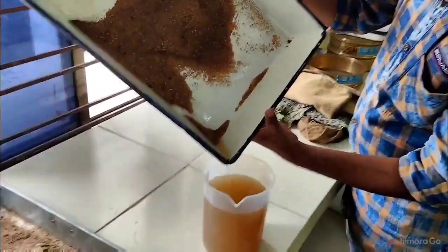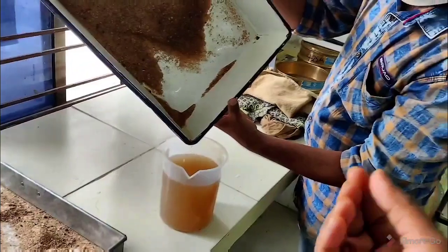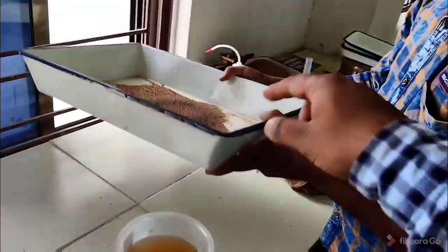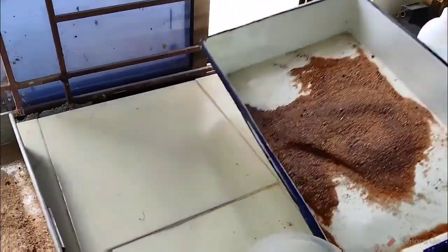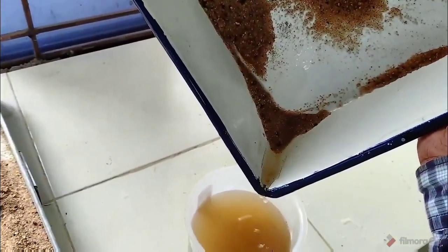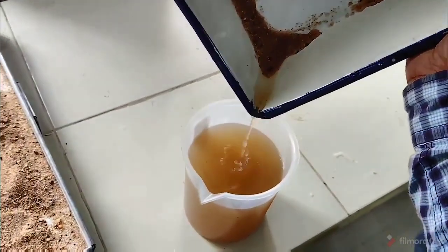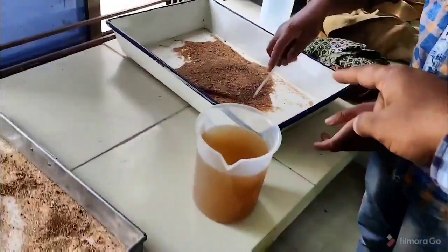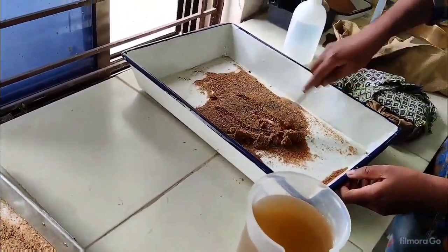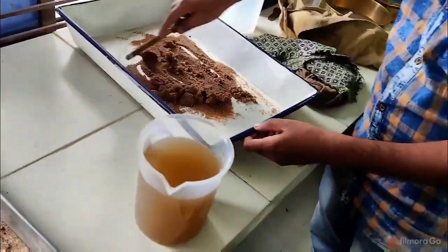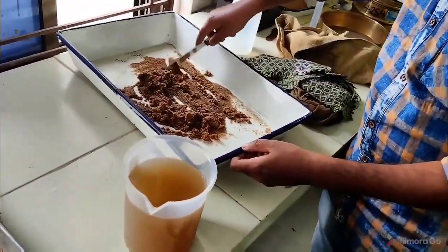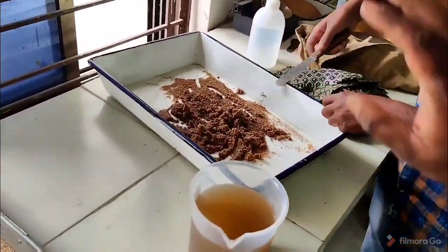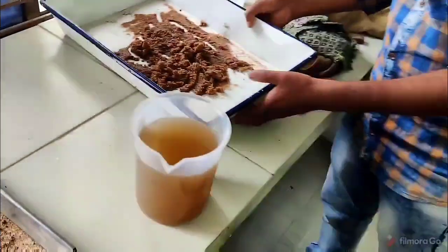It will be separated, but the quantity will be very small, like 1, 2, 3 grams, but still that is very important. Okay, now it is completely decanted, meaning mostly water is poured into this. Now we have to place it inside the oven for 24 hours, and tomorrow after 24 hours we will take the dried weight, which is D, noted in our column in our tabulation. We keep it there. Keep it as it is inside the oven.